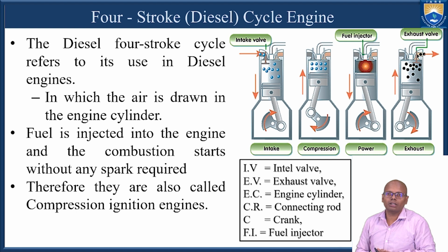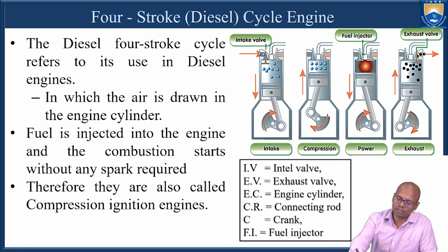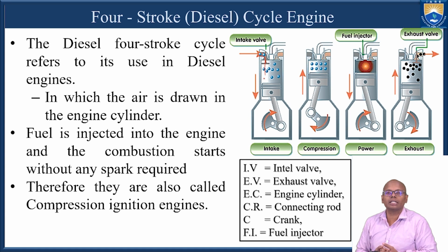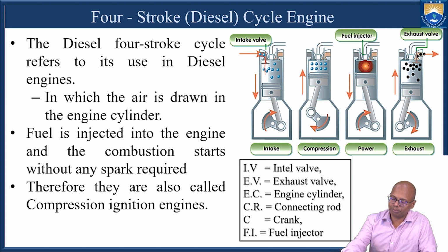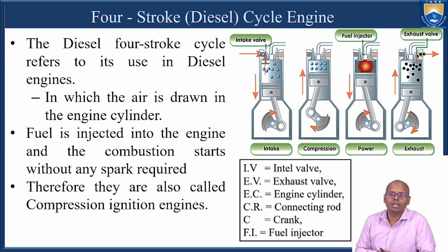In the diesel engine, what happens is we will take only air, and will compress it. At the end of the compression we will release the fuel inside this highly compressed air. So when this fuel comes in contact with the highly compressed air, the combustion starts automatically without any requirement of the spark plug.